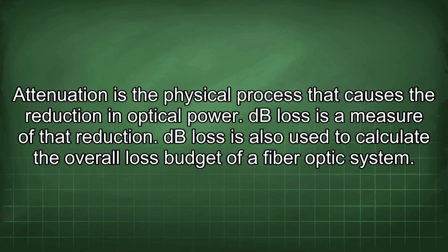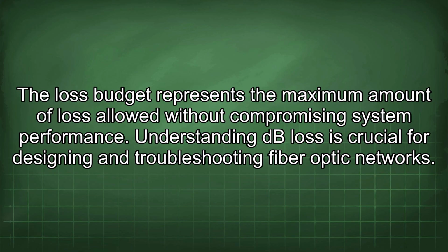dB loss is also used to calculate the overall loss budget of a fiber optic system. The loss budget represents the maximum amount of loss allowed without compromising system performance. Understanding dB loss is crucial for designing and troubleshooting fiber optic networks.